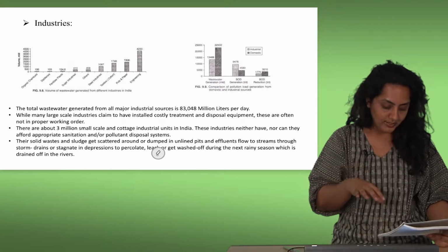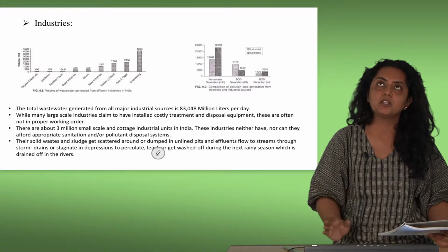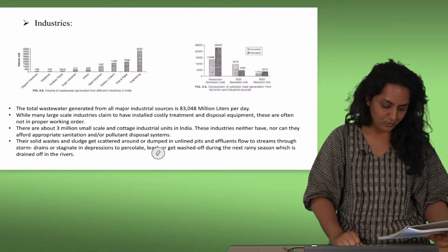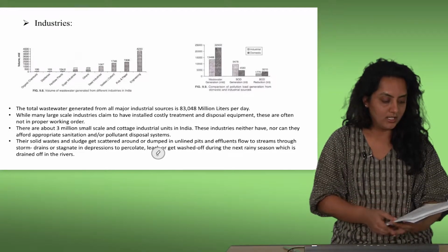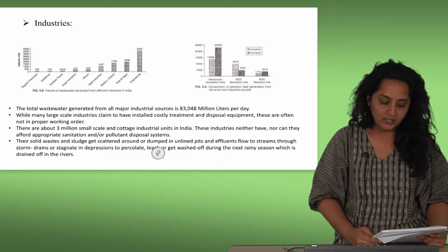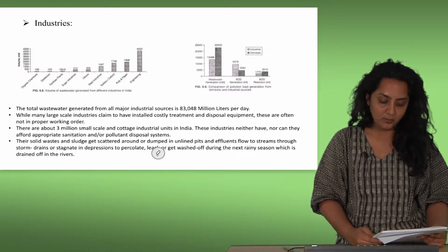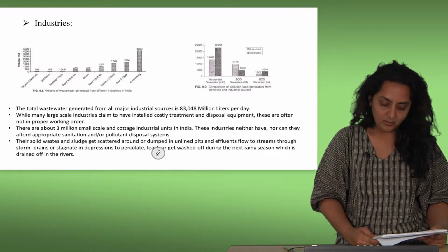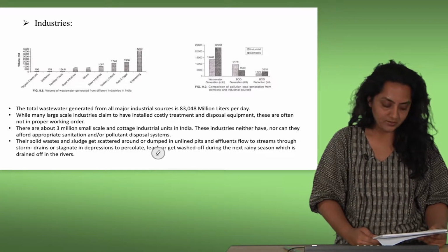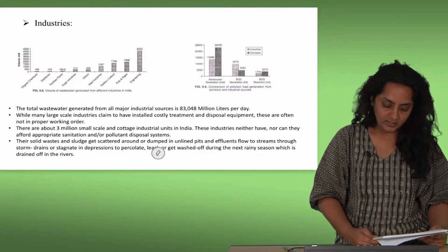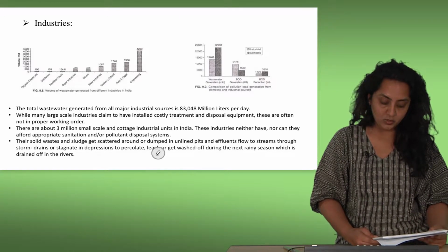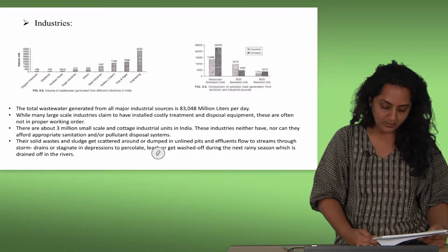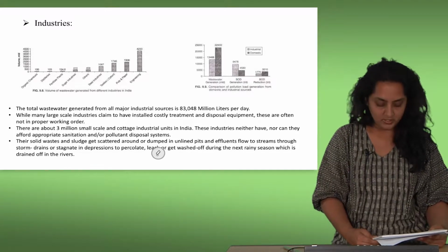The cities that were developed over the banks were not given proper thought about proper sewage and waste management. So nearly 80% of water supply for domestic use passes out as wastewater. Part of the water percolates towards the ground and contaminates groundwater as well. Cities with population more than 1 lakh generate as much as 16,000 million liters per day, but only 70% of the population is provided with proper sewage facility. There are really populated regions around river Ganga, and the Ganga river basin contributes about 1/3 of the total wastewater of entire India, which is a serious issue. As per the latest estimates, out of 20,000 million liters per day of the wastewater generated, only 6,000 is treated before it is let out.